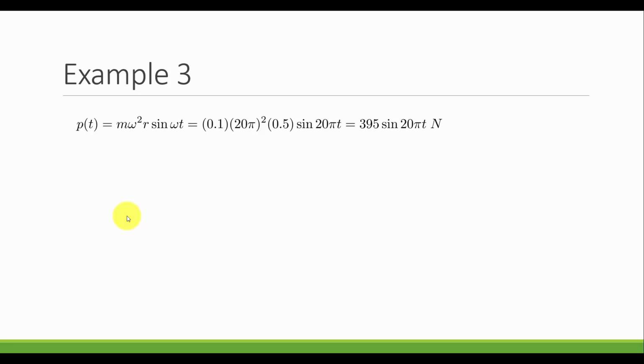So if we were desiring, by designing this vibration isolator, that the output was only 10% of the input, that means that output force in the time domain should be 10% of the amplitude. So instead of 395, it should be 39.5. And we should see it has the same frequency and then maybe some phase lag introduced as well. So if this is true, our design has worked correctly. We're getting only 10% of the input force as output force. So let's verify this using Simulink.